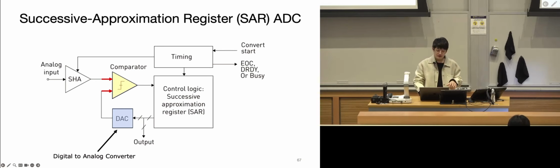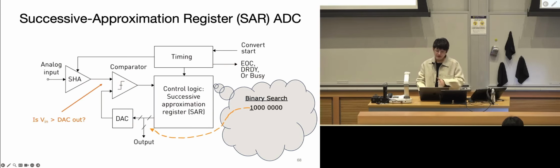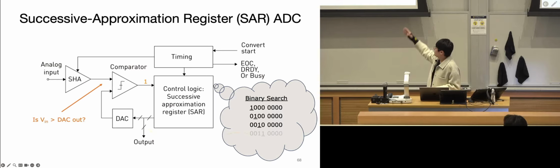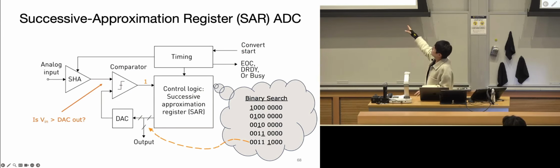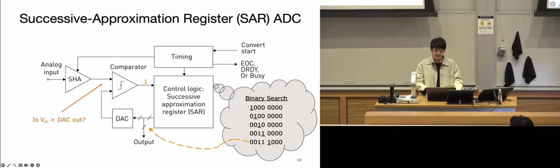and find the closest match. So the worst case would be if we have an n-bit DAC, which will also conveniently usually be the n-bit of the ADC. That n-bit will be the number of steps it needs to reach the value it needs to output in the worst case. So just start from the beginning and then go 1 bit at a time. This is SAR. This also happens to be the ADC that's been used on our STM32 board.